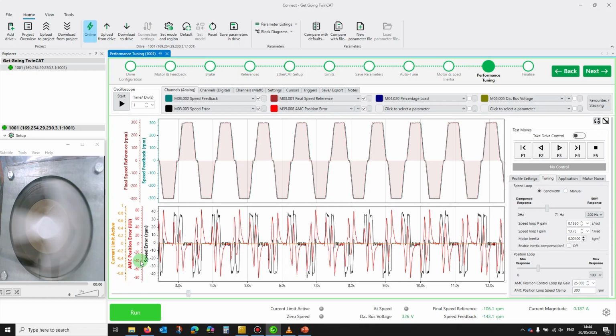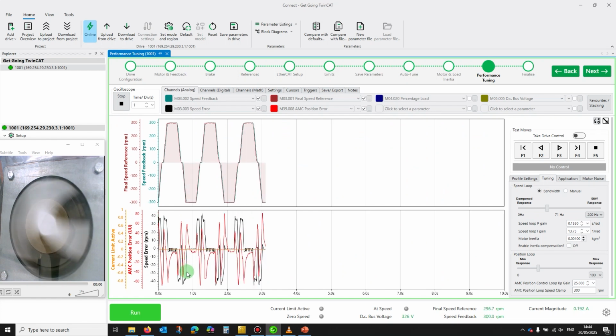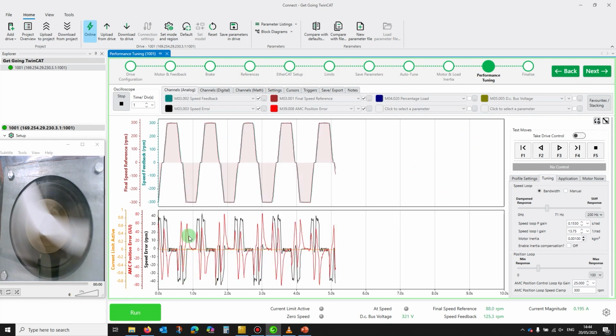Now for this particular application, I know I've got a decent encoder on there. It's capable of about 2 to the power 21 encoder counts per rev. We're only running on 16-bit resolution from that, but I think we can improve this a little bit further. So let's have a look at doing that. If I start the scope again, remember we're looking at improving this red line.